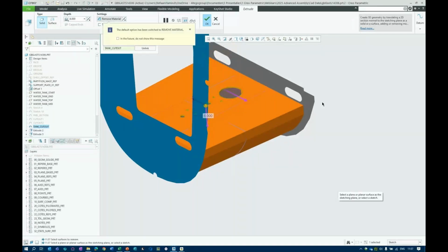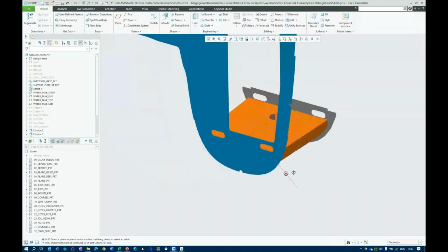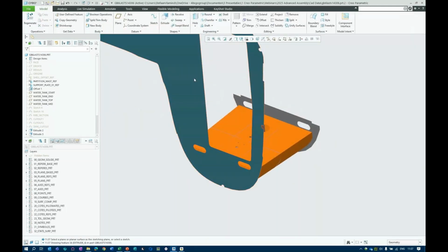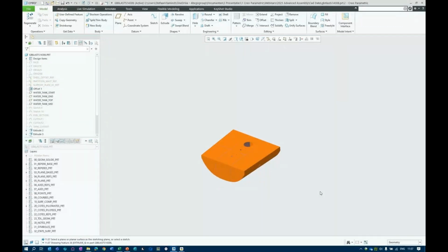-8 because of our thickness. Okay, and maybe this part is created and ready to go. In the end, of course, those surfaces, we don't need them anymore. We can hide them, or we can also put them on a layer that you don't see, because this is your end part, but it is derived from our references that we have copied.